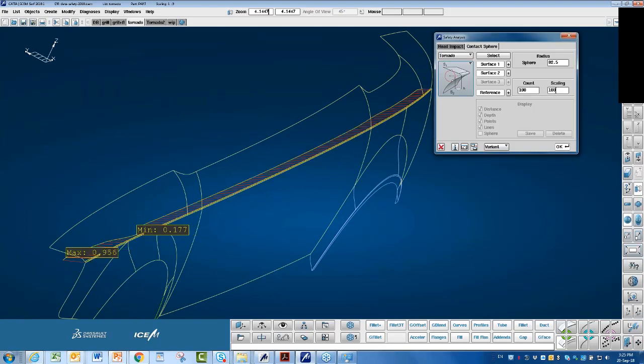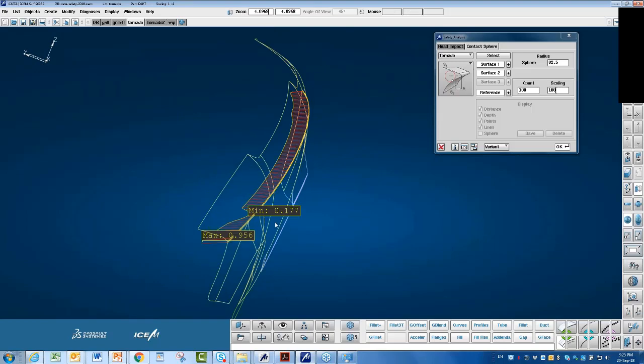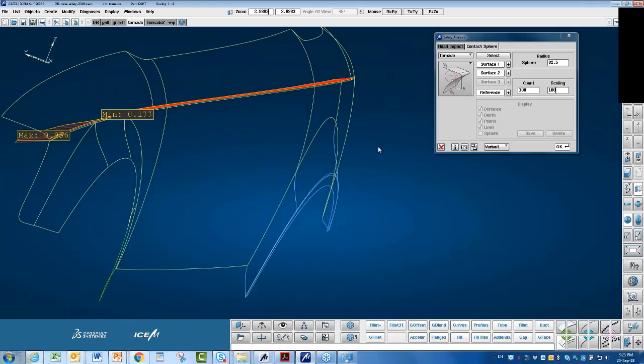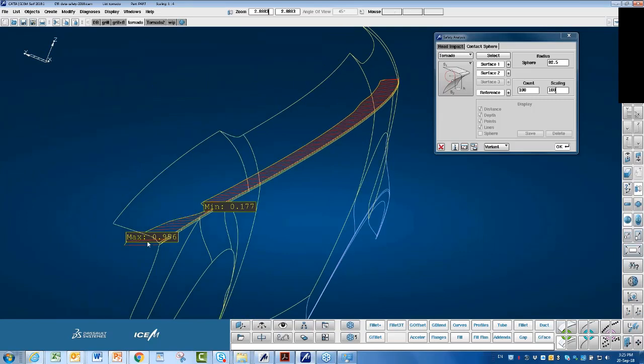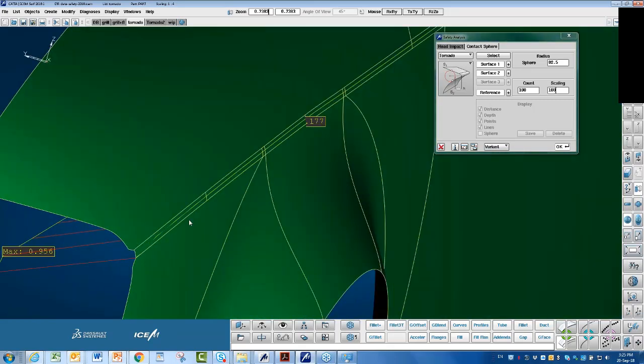All right. So remember, this is the H value. All right, so it's not telling us if our fillet is safe or not. What it's saying here is, so taking the maximum value, it's about 1 millimeter, 0.956, okay? So if you remember, if we divide that by 10, that is the minimum radius allowed for the fillet here. Now, if we take a look at the fillet, we can all see that it's comfortably above that.